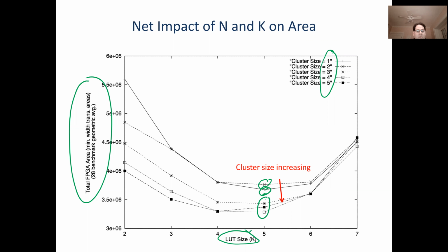Yeah, it's maybe too hard a question. Basically, you add the local interconnect in. Yeah, so actually people guessed this quite well. Immediate addition of muxes. That's basically when you go to a logic cluster of size 2, you add an extra layer of muxing into your logic block, but it's still a pretty small logic block. With only 2 LUTs in it, you don't capture that many signals inside the logic block. So the local interconnect doesn't actually pay for itself. When you go to larger logic clusters, the local interconnect is better able to capture signals and it pays for itself. So that's what's happening here.